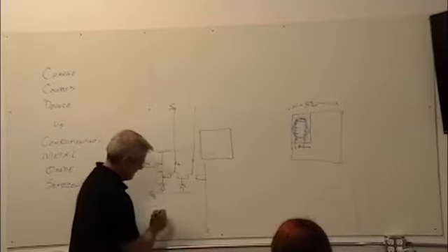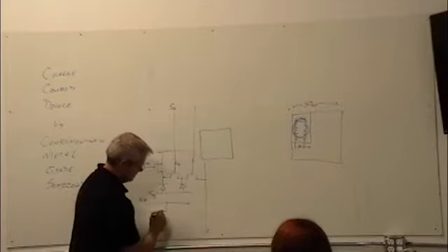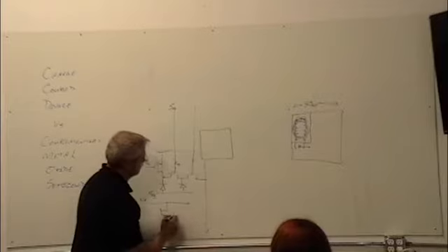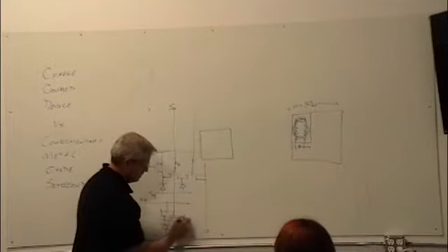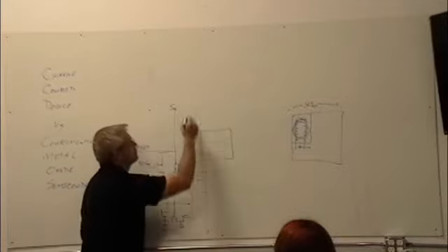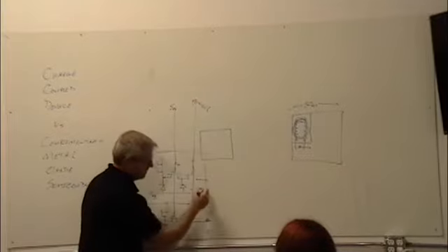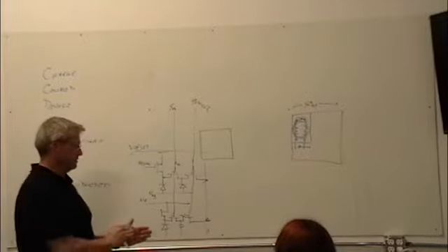And now I've got this thing again. So here I've got V reset, and I've got this switch onto this diode, into that switch, tied together into this capacitor, whether it's a diode or a capacitor, into this row select, and they tie up. And then down at the bottom, there's a big multiplexer that you say, this one, this one, this one, this one.